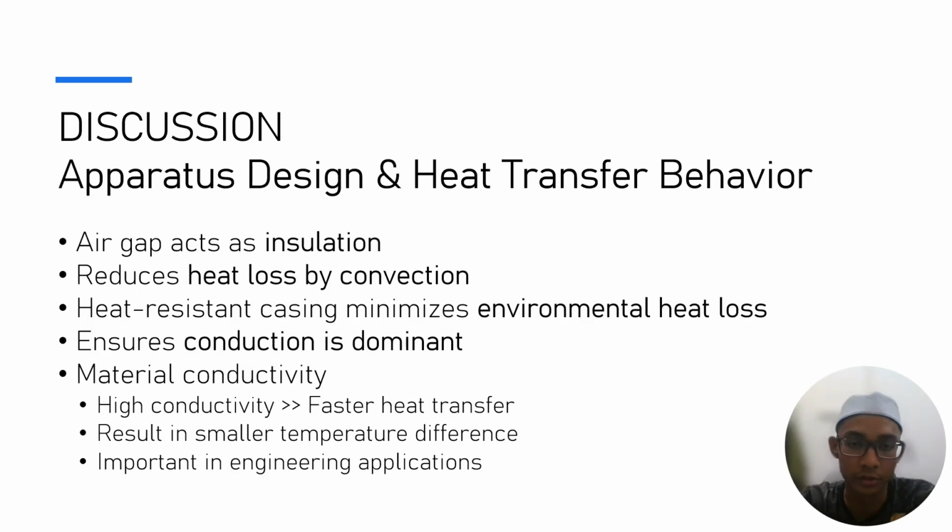First, the apparatus design helps ensure accurate heat conduction. The air gap surrounding the disc acts as an insulating layer, reducing the heat loss due to convection. At the same time, the heat-resistant casing minimizes heat loss to the environment. So these features ensure that conduction remains the dominant mode of heat transfer.